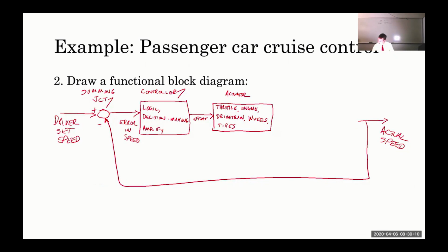So I'm going to call this signal the drive force. We've abstracted everything inside the car between the dashboard and literally where the rubber hits the road as an actuator. And so if we just consider that as a black box, which as EEs, that's all I want to do. I tell the throttle to do something, and then the tires exert a force. That's what we're going to model here.